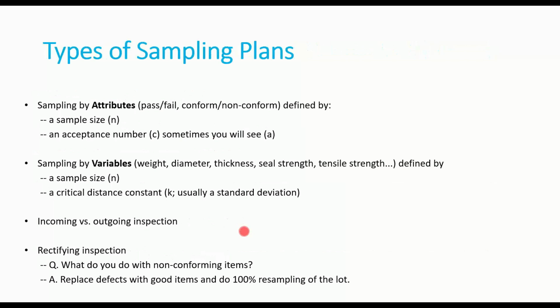Okay, so again, we have the sampling plans by attributes and variables. The kind of data you have will determine whether you use an attribute or a variables plan. And today we're doing attribute. It's the simplest kind. Boy, wait till next month. I'll try to be as good as I can with it, but even it wraps around in my brain a little bit. And you sample some number of items and you classify each item as either having a defect, it's defective or not, it's useful or not, you can use it or not, and you'll have some standard for what that defective item is, like broken, scratched, non-functional, right?